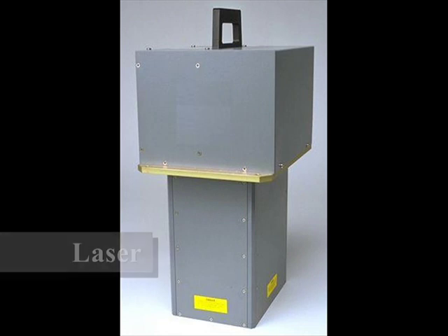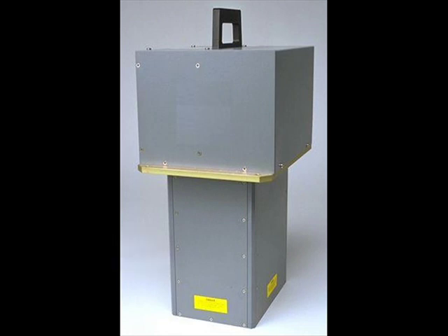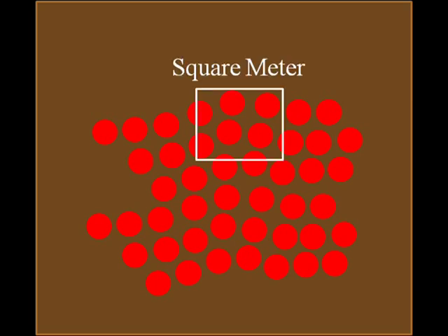The laser is used to record the distance to a target. This is accomplished by emitting pulses of laser light. The pulses travel down from the platform, reflect off the target, and the energy is returned to the collector. The laser can fire thousands of pulses per second. Recorded pulses are called postings. As the laser or its platform moves, these postings form an irregular pattern where they strike the target. This is measured in average number of postings per unit area.